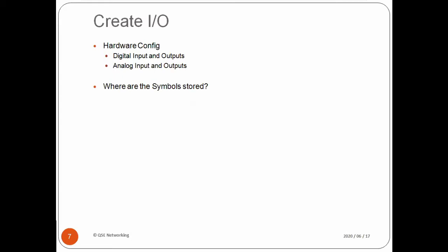Right, so let us go back to the PLC, and let's think about how you would configure I/O. If you remember the little plant we used as an example last time, it was a tank with a pipeline with a pump and a drain valve and a supply valve going to another tank. We had a pump, and then in the second tank we had motor one, which was the agitator. So we allowed for 5 motors and 5 valves for spares in future.